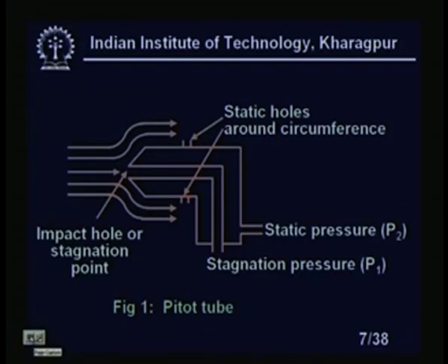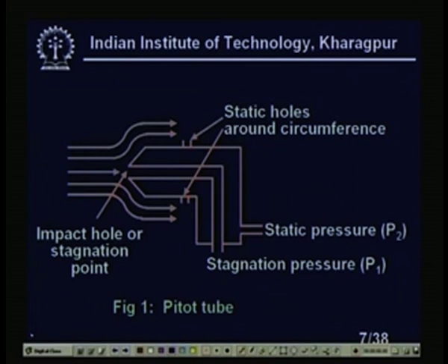So, here you see a pitot tube, look at it very carefully, right. So, you see this is a pitot tube, our liquid is flowing, it is installed in a pipe. I have not shown the pipe. So, the pipe will be there, and inside the pipe it is going. So, it is installed in a pipe, please note, always installed in a pipe, right. So, this impact hole should always be in a direction opposite to the flow velocity.